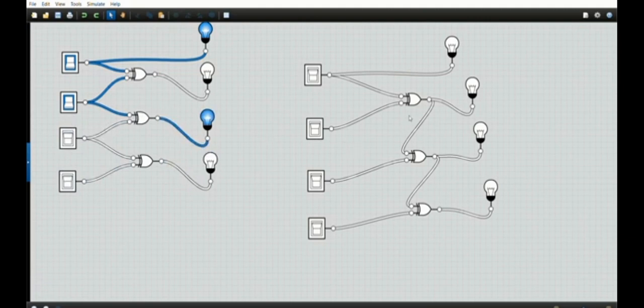So in gray code to binary, we are using 3 XOR gates, and we are going to give 4 outputs. So G3 is directly connected to B3. Here for this XOR gate, we are giving inputs G3 and G2. The output of this XOR gate is connected to this XOR gate as one input, and G1 is connected to this as an input. The output of this XOR gate is connected here, and G0 is connected here as an input. So now if we switch on this,